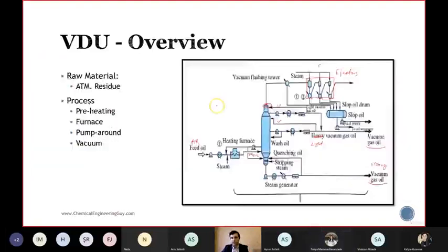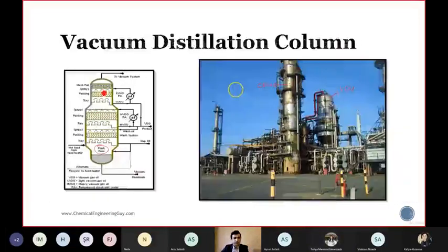The pressure drop comes from the packing, trays, sprays, from the internals of the column. It means that you always have a limitation on pressure drop. Once you see that it exceeds the maximum limit of pressure drop, you start to investigate where it comes from. Maybe you have coking inside the packing, or maybe you have some problems with sprays. Often the trays can move in the column.